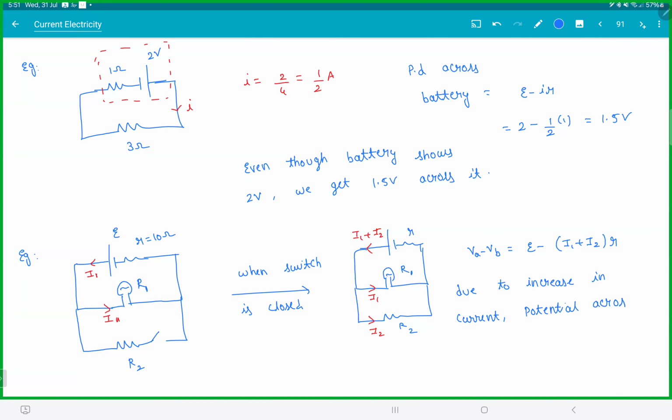So when you start the car, let's say the bulb is taking around 0.1 ampere, the car engine will take around 10 amperes. It takes a large current, but for a short time. So suddenly the voltage drops. If the voltage across the battery drops, then the bulb will be dimmer. The bulb becomes dim. Technically I1 also won't remain the same, but okay. Clear with this? The same thing, reverse also you can do.